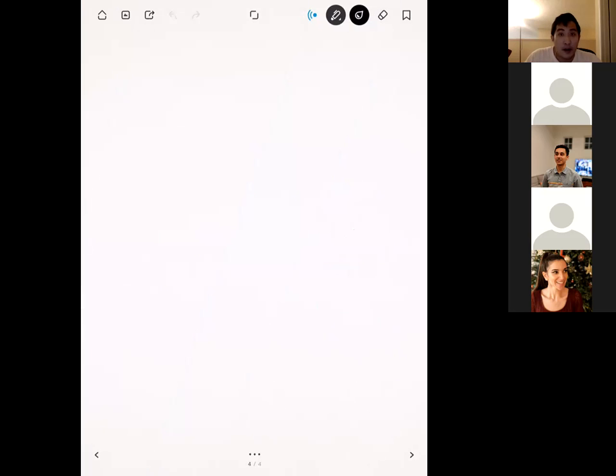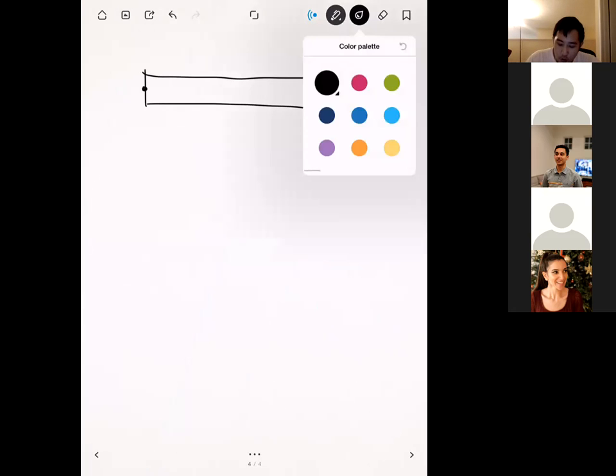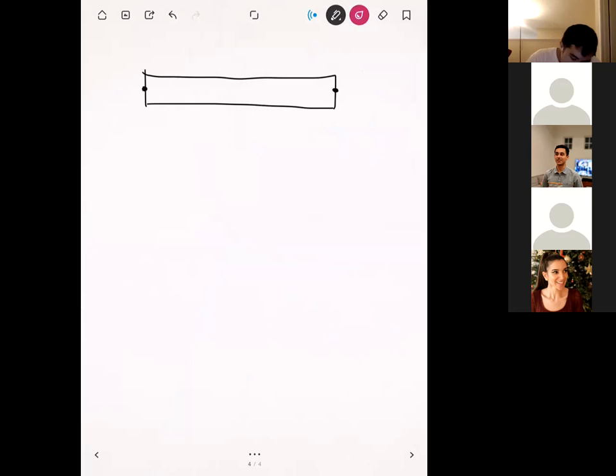All right. Let me draw a figure here to illustrate the work done by the nodal loads. Here's our beam. Up to this point, we have a load that's distributed over this whole beam. But when we convert that to nodal loads, what we have is the following. We're going to have one force that's being applied on the left side. We'll call this node 1, call this node 2. We're going to have F1y. We're also going to have F2y. Those are simply discrete loads that are being applied on the ends.